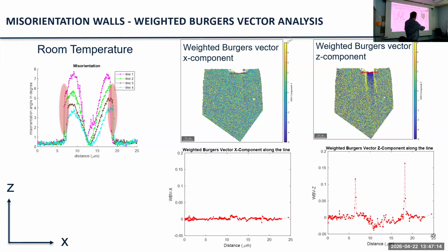It seems in these walls that we are producing dislocations, like the second order pyramidal ones, that are not easy to activate. We see evidence that there's a component of the Burgers vector in the c-axis in the walls. There is one paper where people did TEM on a similar material and loading condition, and they were able to do a g·b Burgers analysis and find these c+a dislocations.